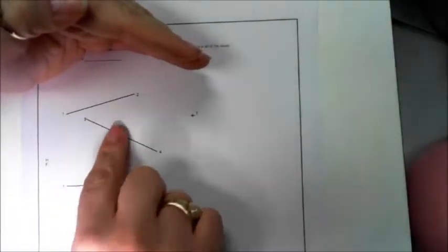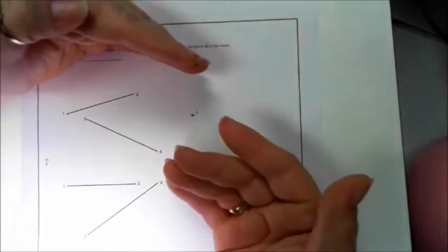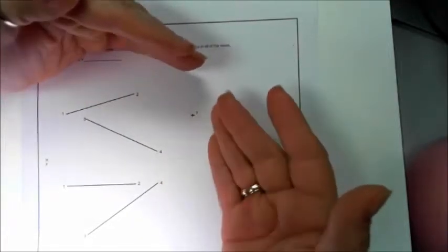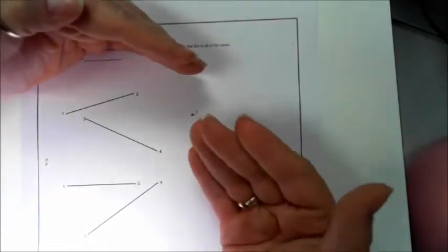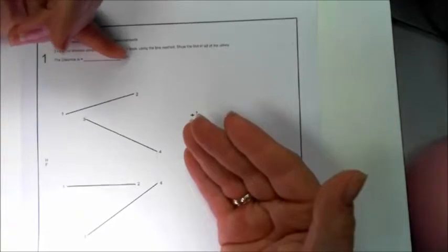You're drawing a roof to a house. You have two different angles where your eaves and everything are coming in lining up. And then you have your ridge line that connects between those two. You need to know what that distance is if you're going to be cutting the material that's going to go between it. You need to know what is the shortest distance between those two lines, because typically that is where your ridge line is going to be, and that's where everything connects and goes together.